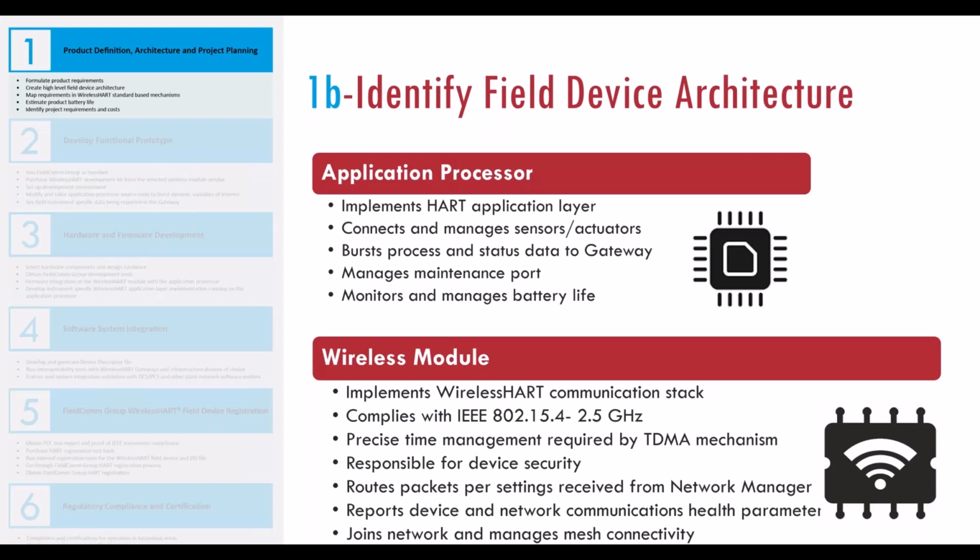The wireless module and the stack is also responsible for device security, which is very helpful since the application layer does not have to do much, right? It also routes packets and sends data on behalf of other instruments that are part of the network, and is also obviously responsible for joining the network and managing this mesh connectivity.